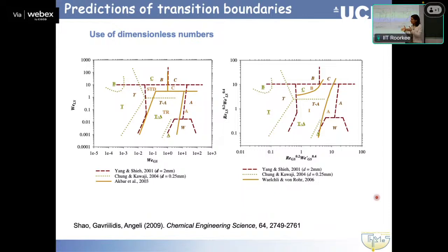Just generally for flow pattern transitions, it doesn't look possible that all flow pattern transitions can be predicted by using the same dimensionless numbers, because it's different phenomena that are responsible for this. Not for all flow patterns. So what I was saying is that this is one level: let's try to use some dimensionless numbers or even simpler coordinates, and we predict everything. It's simple, it's easy to use.